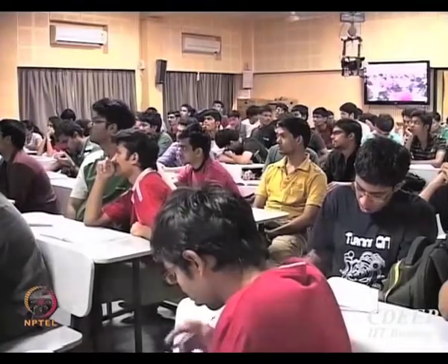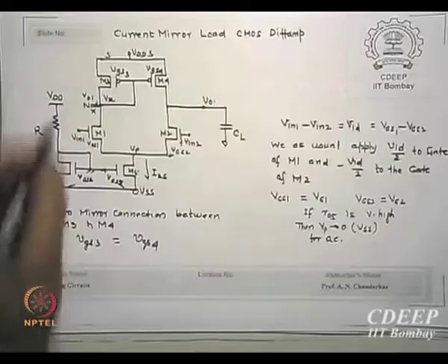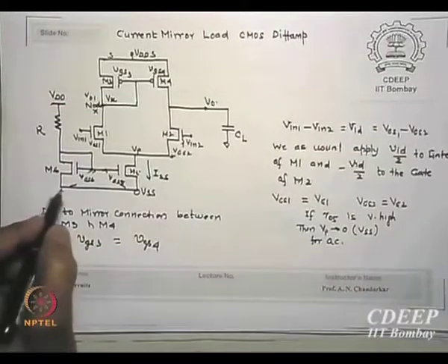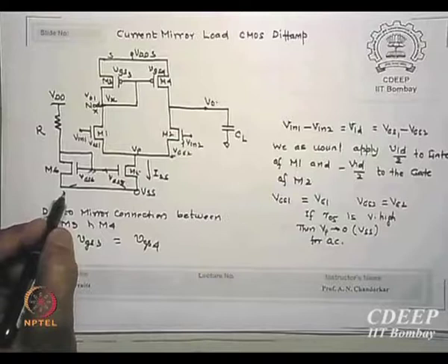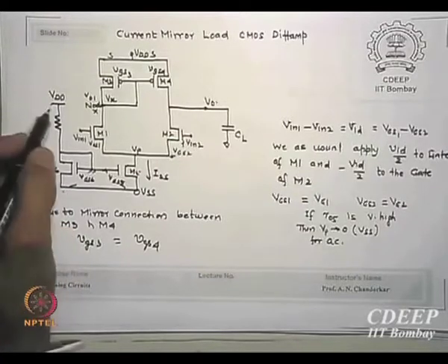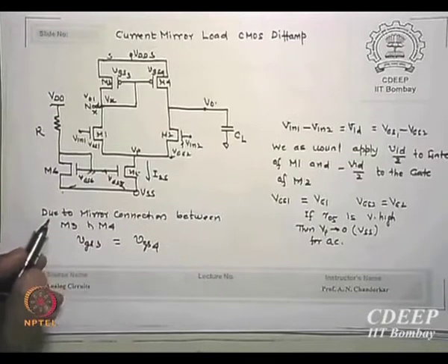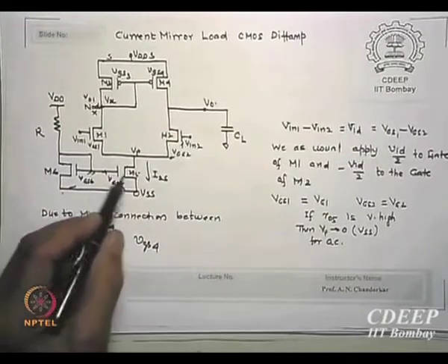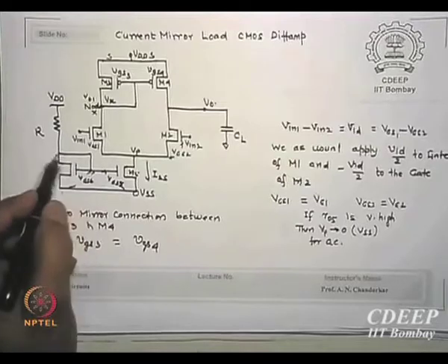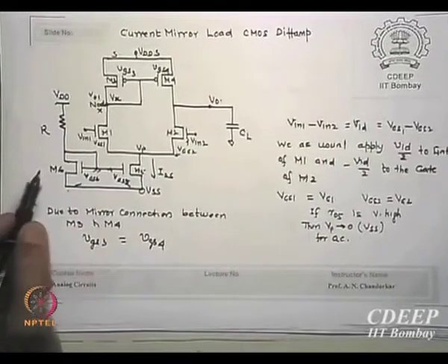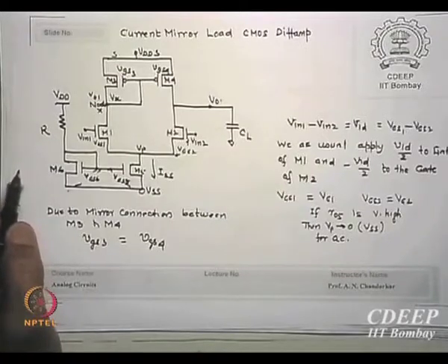No, because with this value itself I have calculated the current, you understood? Here I am not treating ground, here I am treating minus VSS as the value and VDD is this value, so when I calculate reference current I am using VSS there. By making this choice of the gate, I am ensuring this VGS is positive enough, greater than VT, with VSS.